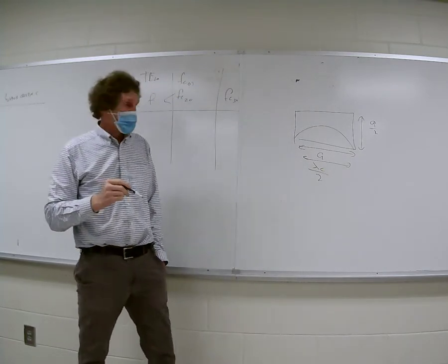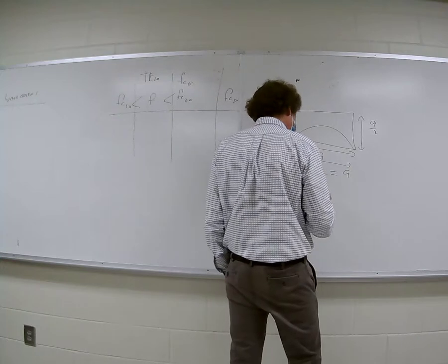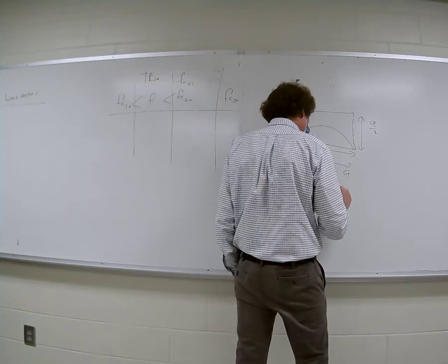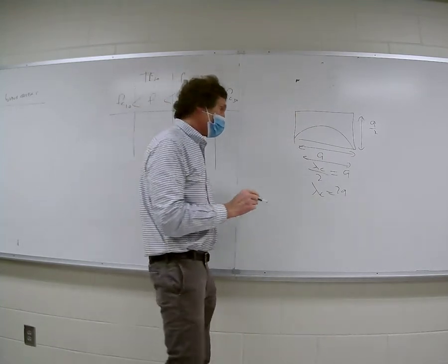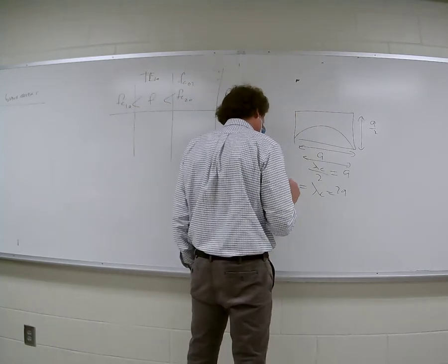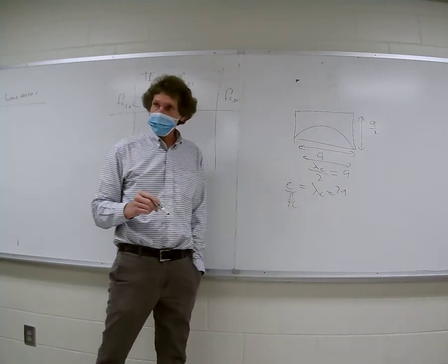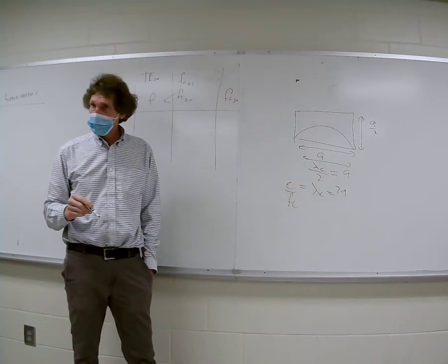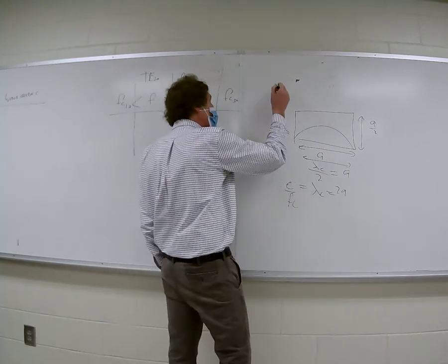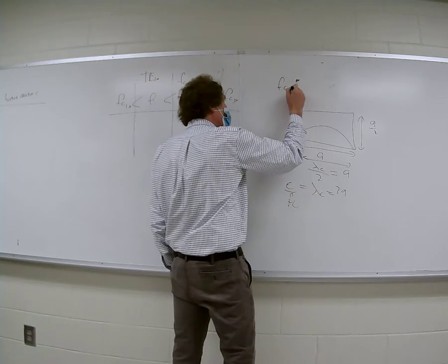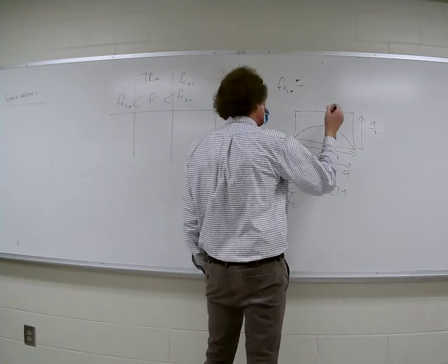All right? So you would set this equal to A, right? And then you'd say the cutoff wavelength here is A times 2, right? And then the cutoff wavelength is equal to, well, if you think about it, C over F cutoff, right? If it's air filled. Does everybody understand this? And from that, you can get the cutoff frequency, and this would be for the 10 mode. And you would simply say it's going to be C over 2A.